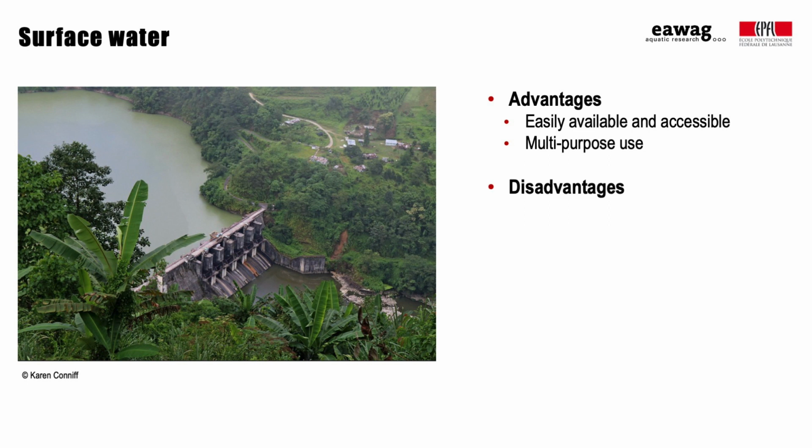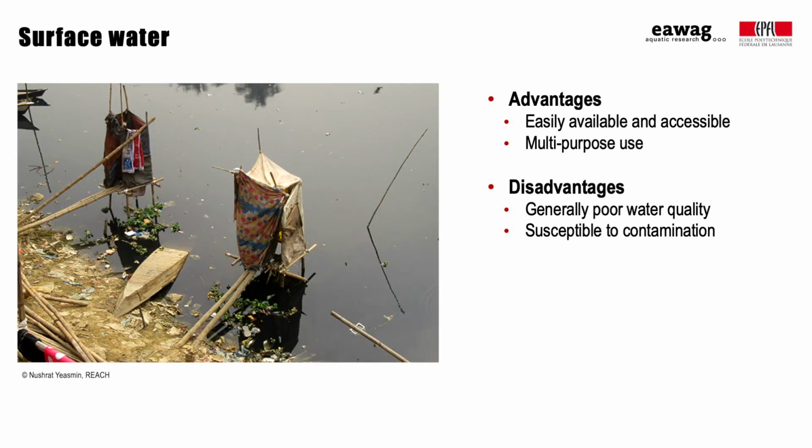The water quality of surface water sources should be considered poor in most cases. Contamination of surface water is likely through poor sanitation practices like open defecation or from discharge of raw effluent or from surface runoff from surrounding anthropogenic activities. Seasonal variation can impact water quality and quantity with increasing turbidity in the rainy season and high water loss due to evaporation in the dry season.